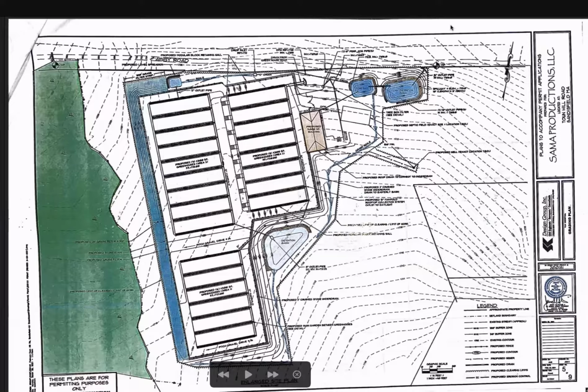So in an effort to make this site dense and as small as possible and to avoid excess earth removal and earthwork, this is what fit. I tiered the site. I tried that a couple of times to get these elevations set. There's 5 feet of grade between the lower tier and the upper tier, and then I raised this one up. It's 7 feet higher. So as you lay out these pods of greenhouses on this site, it's really related to the lot configuration and the topography.